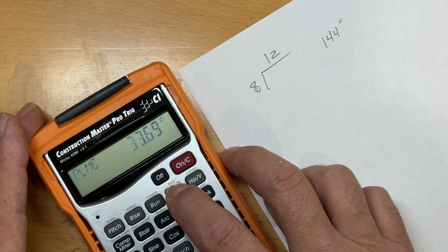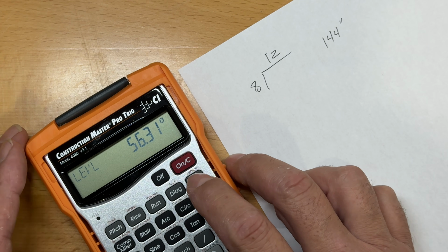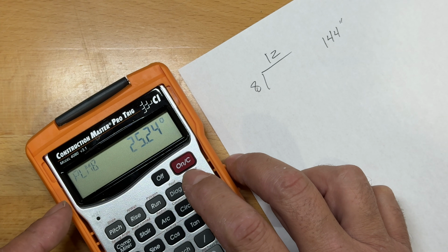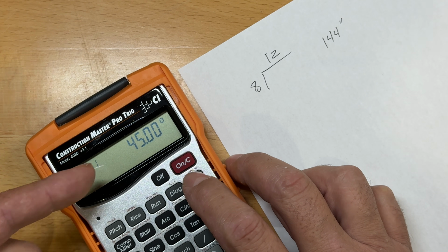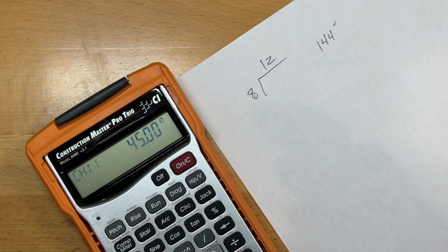And then if we continue to hit diagonal, it'll give us the plumb cut and the level cut. Then if we move over to the hip, it gives us the length of the hip rafter. It'll also give us the plumb cut and the level cut for the hip rafters, and it'll tell us the cheek cut, the double cheek cut at the bottom of the hip rafter, which in a standard hip is going to be two 45-degree angles.